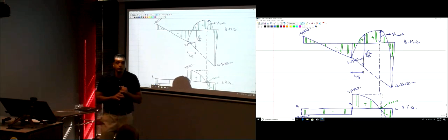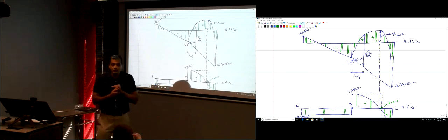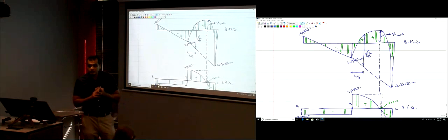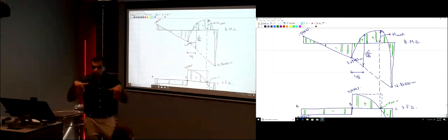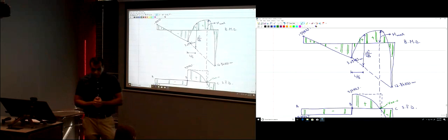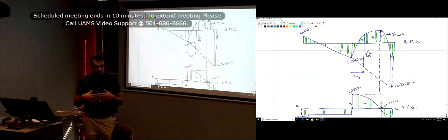So I need you to write all the constraints regarding the dimensions, regarding the weights. So the weight of your structure, there is a limitation for the weights, okay? There are some constraints regarding the deflection, okay? When you load the bridge, there will be some deflections. Those deflections can be any value, but they cannot exceed a certain limit. That's the constraint, okay?